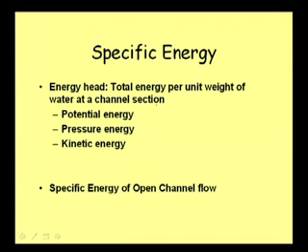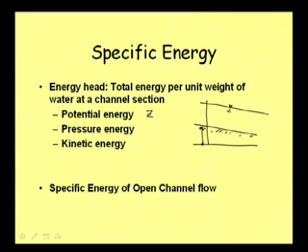And when we say energy, we always talk about the energy at a particular section. Potential energy, as we could see, is due to the position. In a channel, by potential energy we always talk of the height up to the channel bed, Z. Say water is flowing up to this much level.